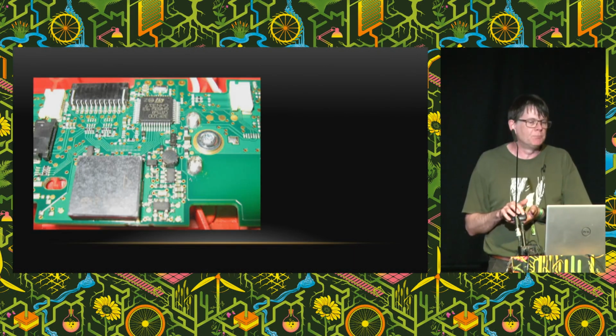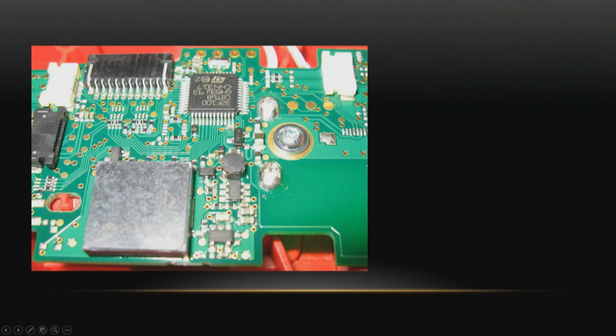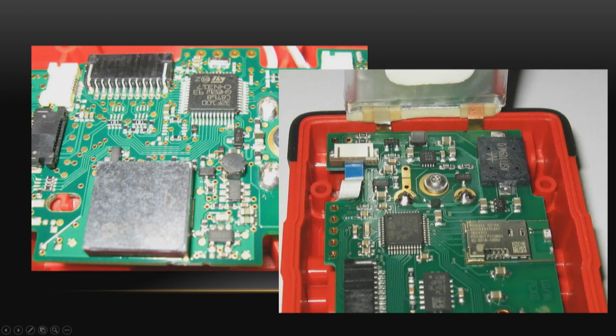That's the Leica board. You can see there's a couple of big solder blobs where the battery connectors join. So you have to desolder that, take out the bolt, take off all the ribbon cables, and solder in this replacement board. And this has got, I think, an STM32 microcontroller chip on it. It's got a Bluetooth module, and it had the IMU components, I think three separate ones for the three axes,